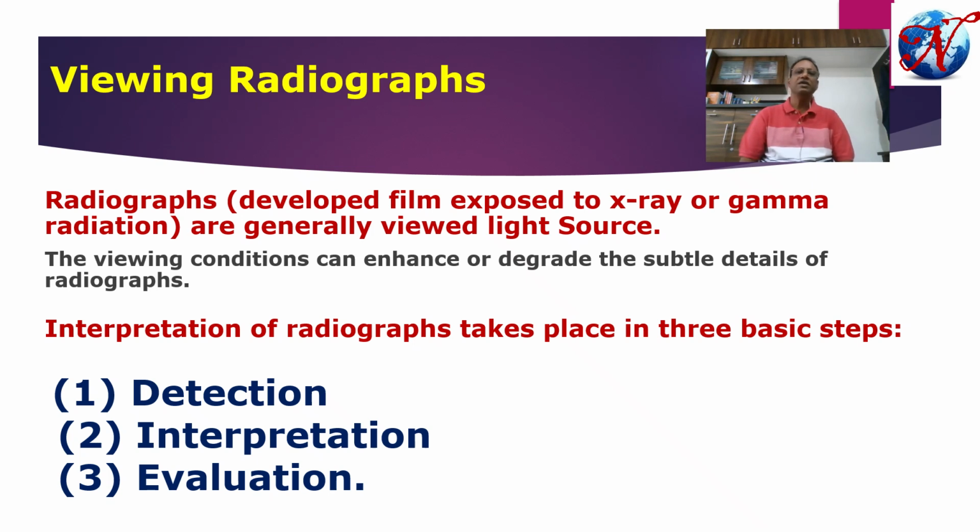What is the job geometry? Is it pipe to pipe, pipe to flange? What is the configuration, pipe to any kind of fittings connection? So first of all, as a good interpreter, we are required to have the information of the inspection part: what is the thickness and whether there is any misalignment or not. These kinds of general information are the part of detection.